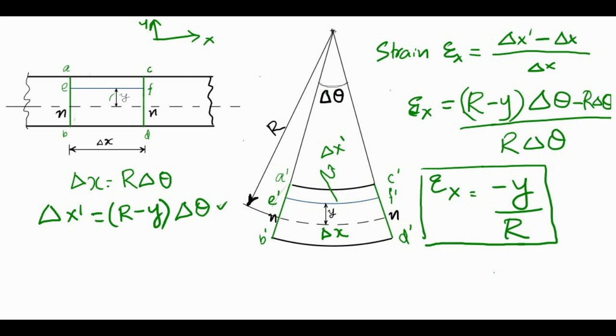Okay, if we want to find the strain in a layer which is some distance d away, in this layer AC, previously it was AC, now it is A dash C dash, so we have to give this distance instead of y. Why this negative sign? The negative sign is due to the nature of bending. Here we take y in the positive direction, that is the upward direction.